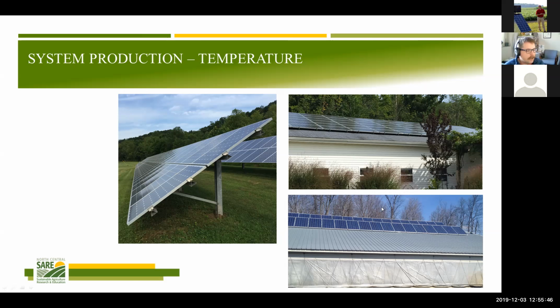Of the 2 roof mounts on the right-hand side, you can see one of them changed the angle to try to gain some production. I would say in the current establishment or best practices for solar, I wouldn't do that. I would not change the tilt angle of my solar, because I'm adding costs of racking that I don't really want. Plus, in some ways, I'm also harming the aesthetics.